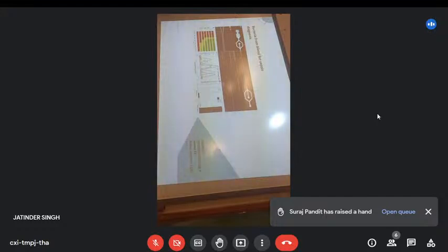This graph here gives you a little bit of an idea of the efficiency of the separation, where we've got 2 micron and 5 micron particles. So we're not really talking about a huge difference in size here, a 3 micron difference. You can see that the 2 micron particles were very selectively collected at one outlet, whereas the other outlet was highly selective for the larger particles. Very minute difference in size between those particles, 2 or 5 micrometers. Still, we can separate them based on the differences in viscoelastic forces.